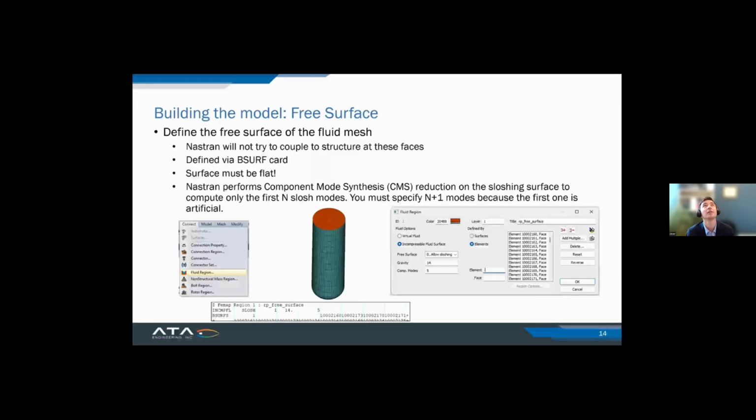You might have to explicitly cut out the baffle in your fluid mesh to make sure it's properly coupling. And then I don't know if the fluid can couple, if you only have a single layer of elements that represent your baffle, I'm not sure if the fluid can couple both on the top and on the bottom. So maybe you would have to do 2 plate elements, stacked.